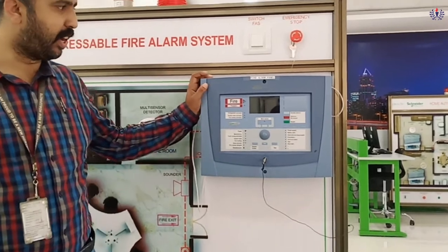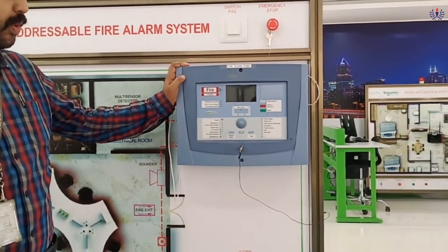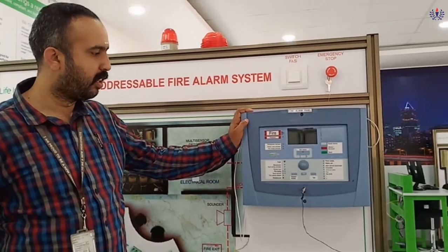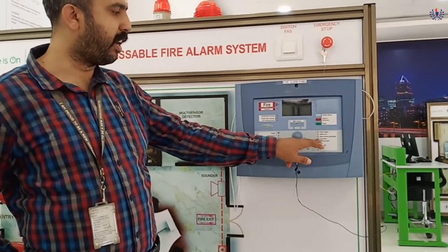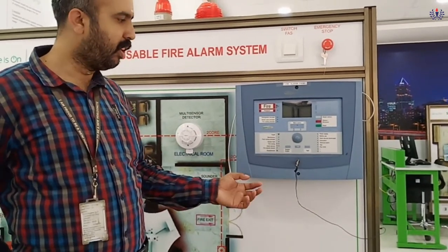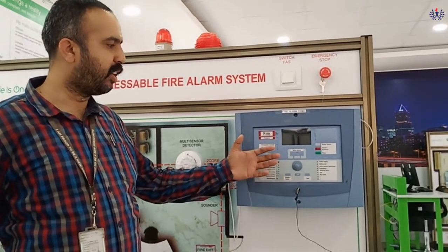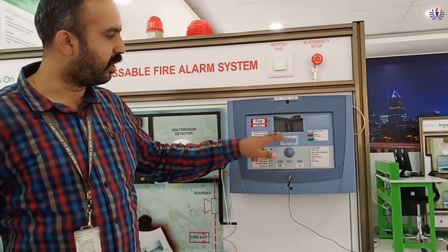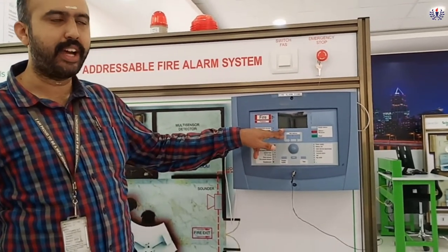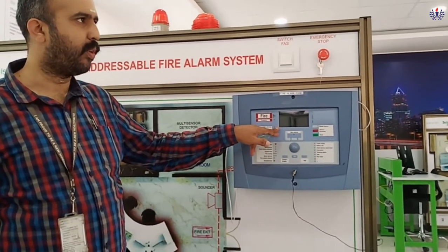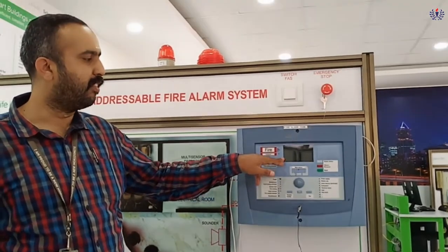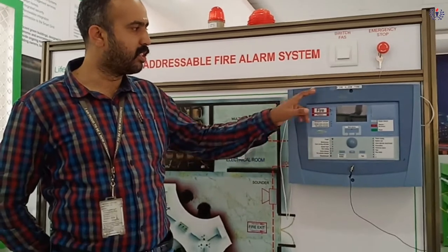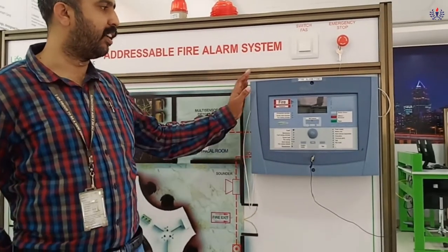So this is the fire alarm panel. In this, we are going to manage all the input devices as well as the output devices. Here you can see the power supply, and there is a battery backup also. Here you switch it on, and we can see all the parameters to be managed. And in this screen, you can see the location where the fire or smoke or what type of fault has happened will be detected. So we can easily identify the spot. Okay, so this is the purpose of the fire alarm panel.